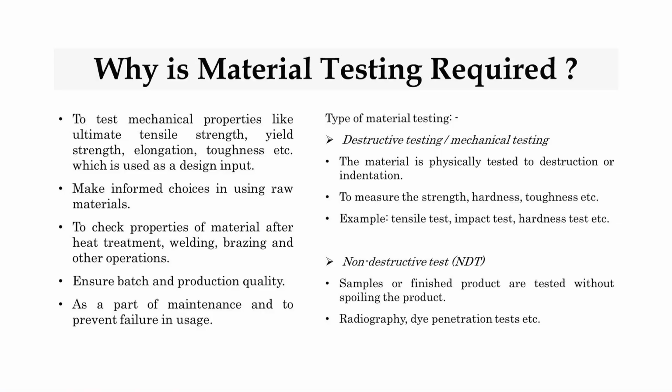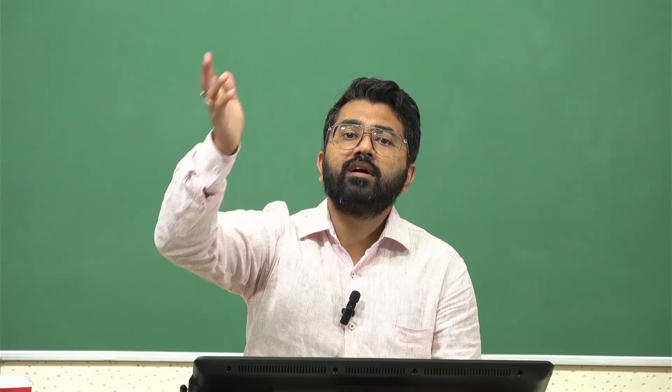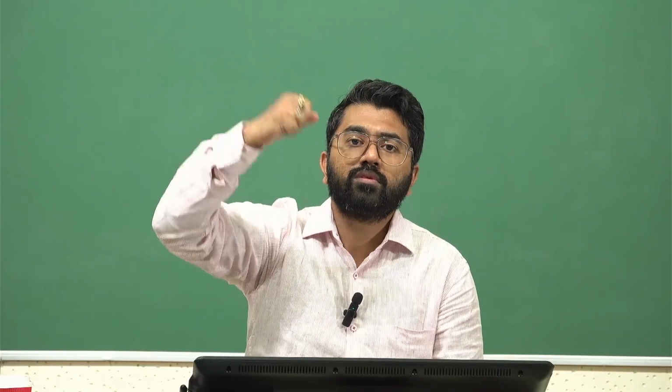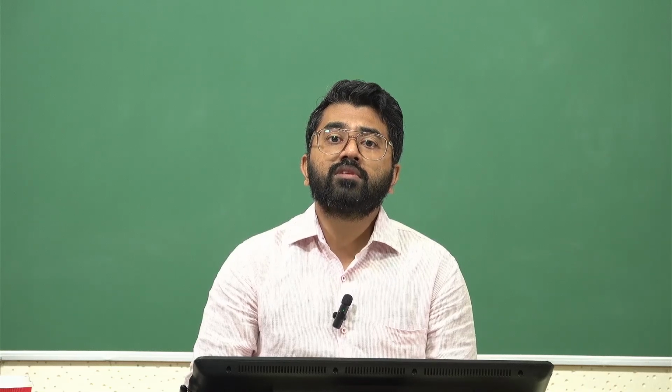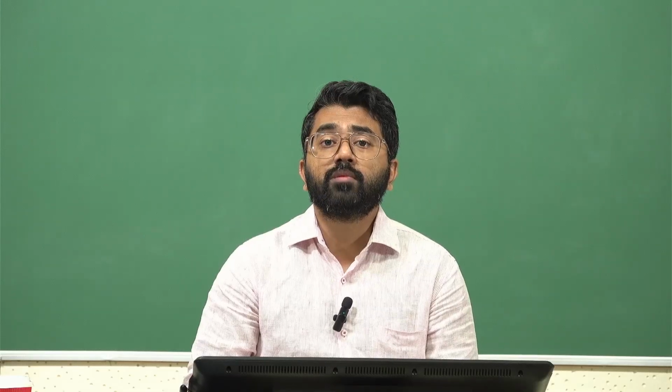Some techniques such as radiography and dye penetration tests are sometimes also used for non-destructive testing. Also, tensile and compressive tests can be non-destructive. They do not have to be carried forward till the ultimate point when it breaks, or when you push it and it completely crushes, right? So destructive and non-destructive has a thin line. You can do non-destructive tests even with the machines where you can perform destructive tests, depending on the load limits and other things, and you have some other techniques as well which you can implement, right?